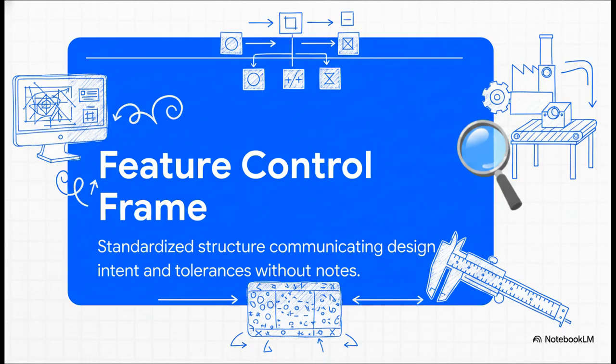Think of the FCF as the absolute Rosetta Stone of manufacturing. It takes your theoretical, perfect design in your CAD software and translates it into a measurable, physical reality on the shop floor. It bundles every single rule for a specific feature into one neat little rectangular box.